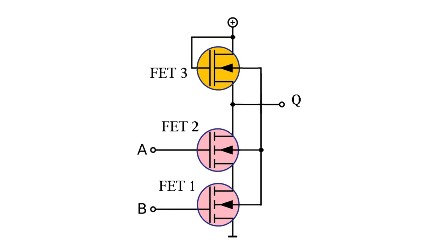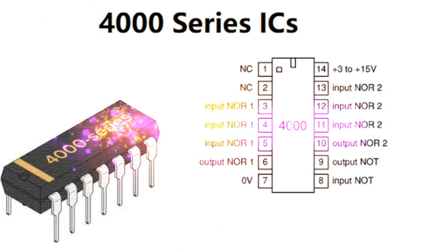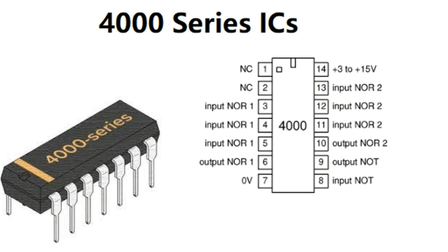Only when both inputs A and B are held high at logic level 1 does current flow through the corresponding MOSFET, switching it on, producing an output state at Q equivalent to a logic level 0 as both MOSFET, FET1 and FET2, are conducting, therefore producing the switching action representative of a NAND gate function. Improvements in the circuit design with regards to switching speed, low power consumption and improved propagation delays has resulted in the standard CMOS 4000 CD family of logic ICs being developed that complement the TTL range.